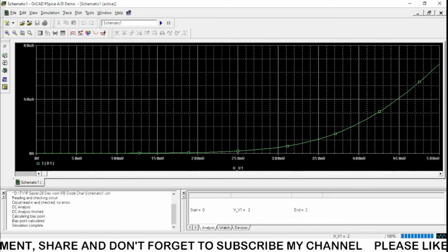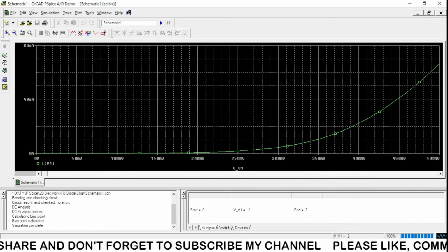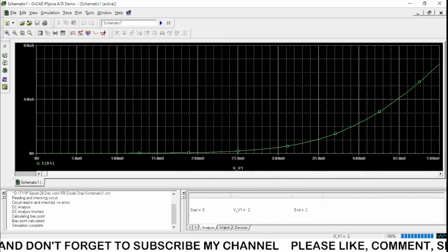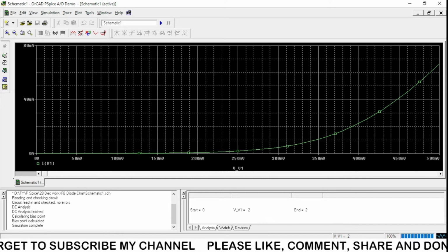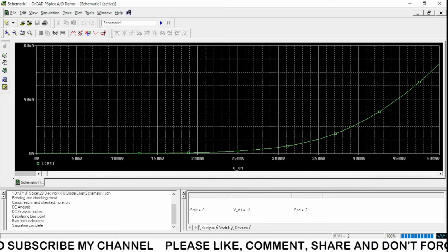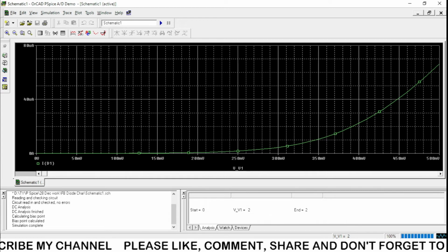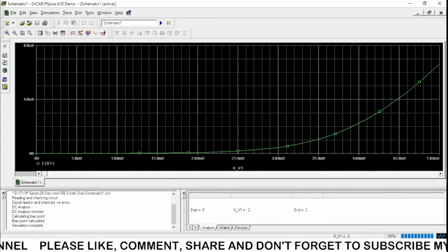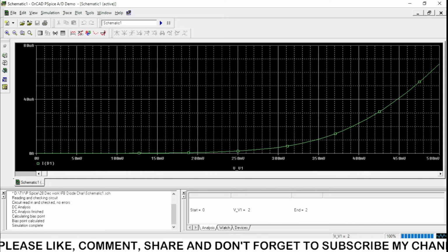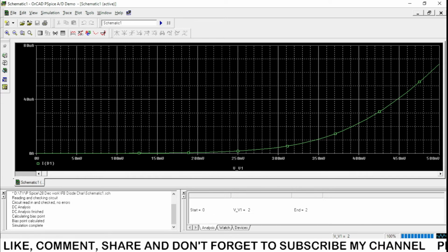So if you need to find out the knee voltage, just take this particular graph at the back. We can draw a line over here, and we can see that at 300 millivolt this will be the knee voltage. So this is a germanium diode, so that's why we are getting approximately 300 millivolt or 0.3 volt.